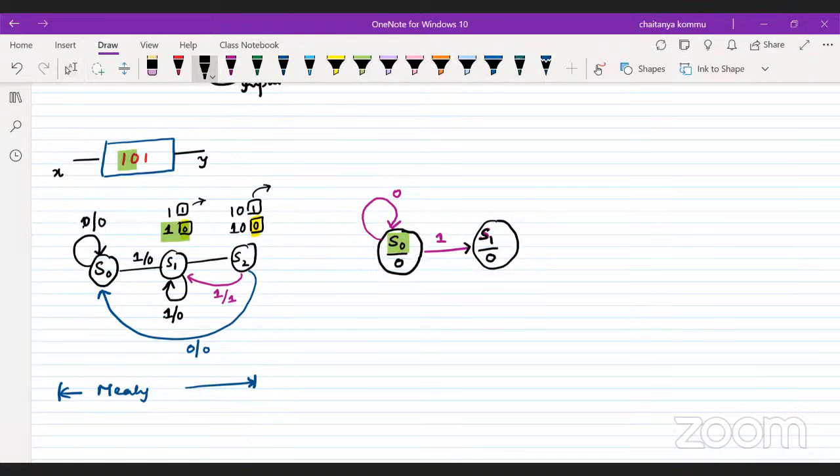So in the second state, we observe that 1 is detected, and a sequence of bits is coming. What if the second bit is logic 0? What if the second bit is logic 1, for example? First consider logic 0. As I mentioned, logic 0 is not a valid bit to start the given sequence. Our requirement is 101, so we can start the sequence with logic 1.